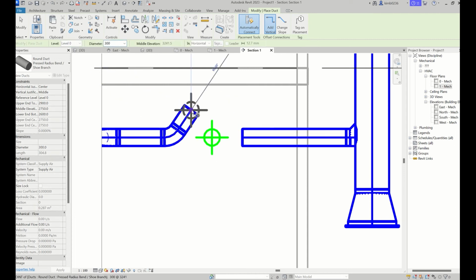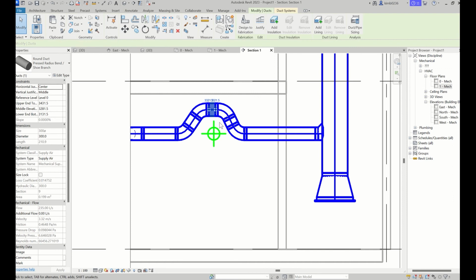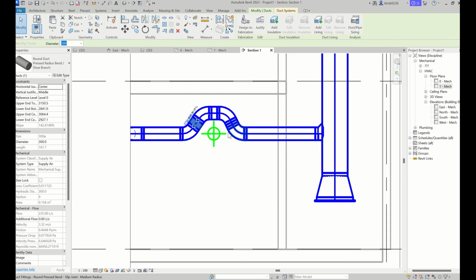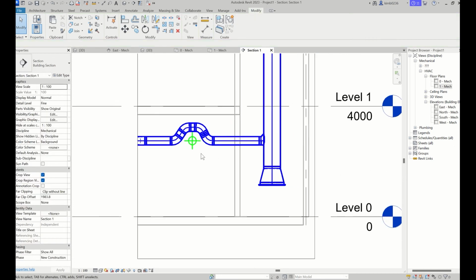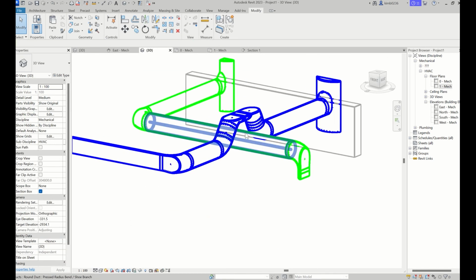I've deleted that because I don't think the ceiling cavity is going to be that big, so let's make it go over. We'll use all the space we have. Now if I select one of the segments, you can tap it with the arrow keys and move it up, down. If I select the left one, I can move it in so it's got a nice tight fit. It depends how accurate you need to be with these things. Let's find the other clashes and do the same.